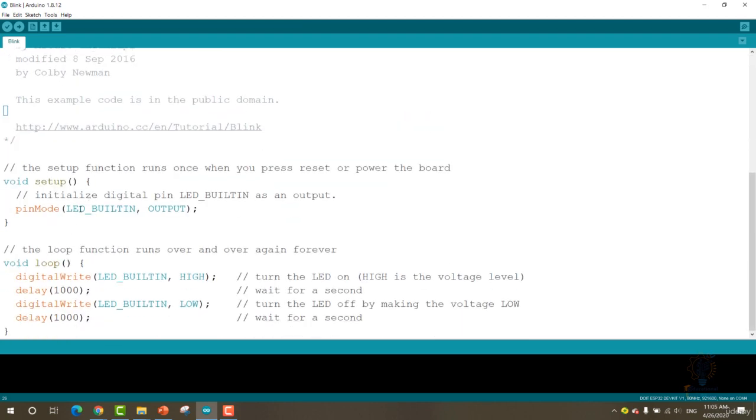We have the LED set to default, which is LED number 13 on Arduino. So we need to change this LED number. As you know, the ESP32 has a built-in LED that is connected to its general purpose input-output number 2. It is important to check if LED_BUILTIN is automatically recognized by the IDE. If not, you must add to the code a line like this.